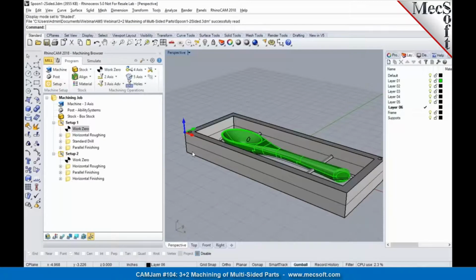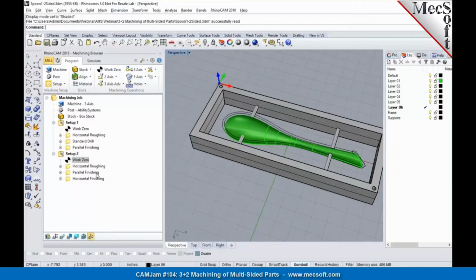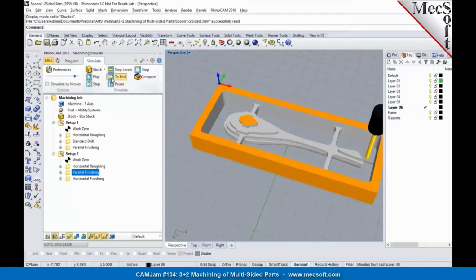When you flip the part over and machine it, if you maintain the same edge, you won't run into any offsets. The part will remain square. So I'm going to use the same edge in here. I'm using the northwest corner to establish the origin, and now we have a roughing operation and finishing operations programmed right in here. So you would basically reorient the part on your machine tool, and then you would be able to run your machining operations for roughing, finishing, and final finishing operations.